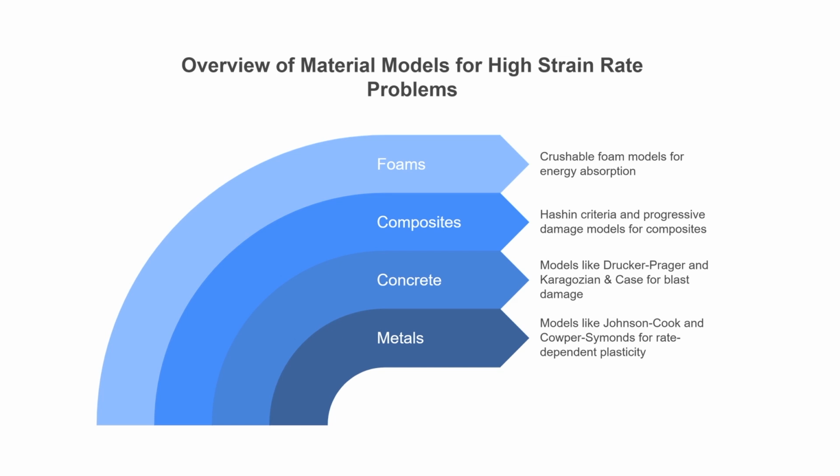Concrete is the most tricky material that is being used, because concrete itself is a very heterogeneous type of material, and different types of material models like Drucker-Prager, KC models have been used, but they are continuously being updated, and still the concrete material modeling is not, I would say, in a very mature stage. But what we try to do is that we try to test in the laboratory and try to put this material characteristic in the concrete and update it always, so that we have a very accurate representation of the concrete material models.